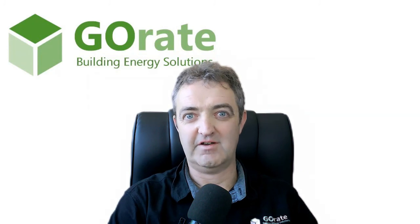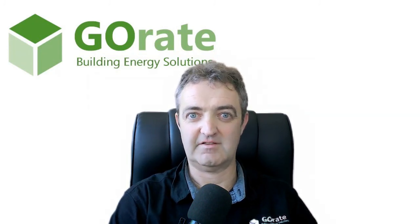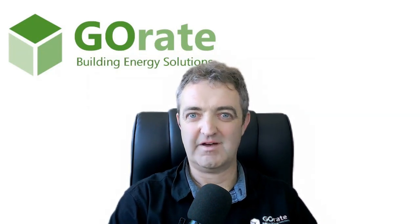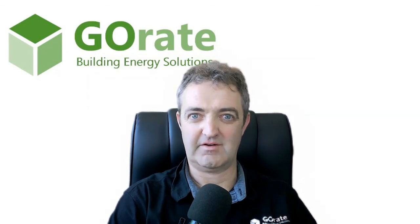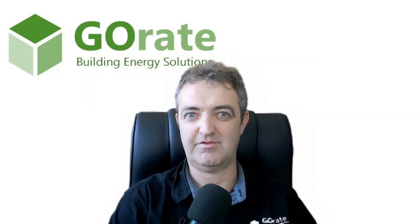Probably around the 5 air changes per hour is what we'll achieve, which is an excellent improvement over what it currently is. It will dramatically improve the energy efficiency of this house and also the indoor air quality and the comfort. So I think we can end up with a very good outcome just by doing some simple things to address the air tightness of this house.